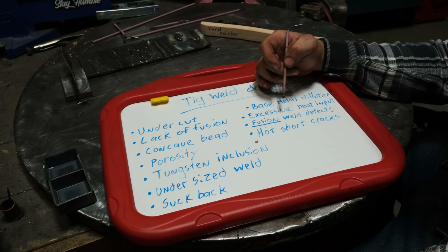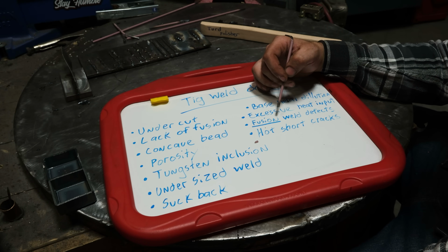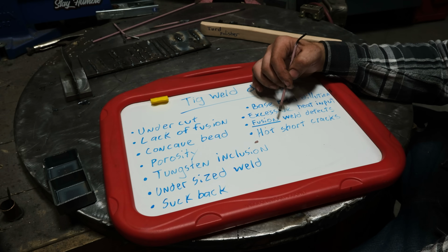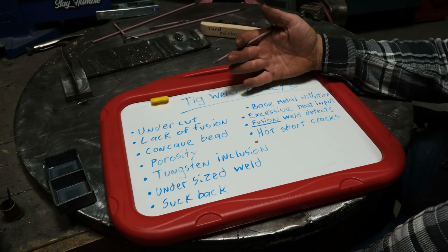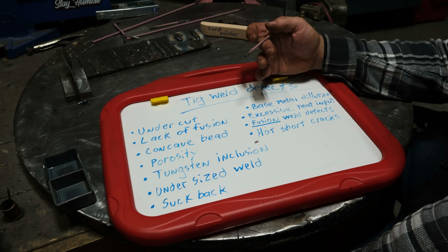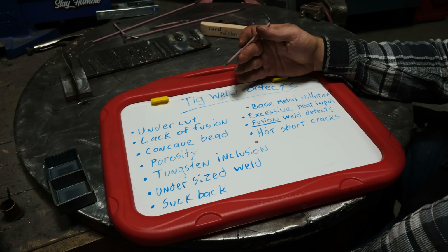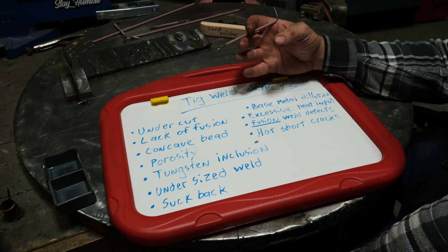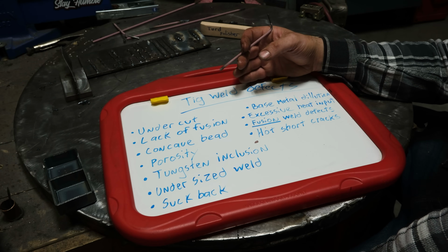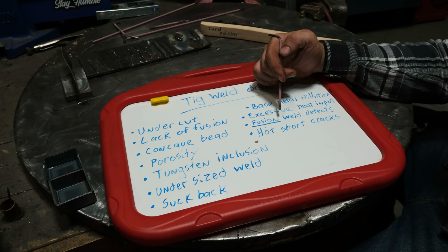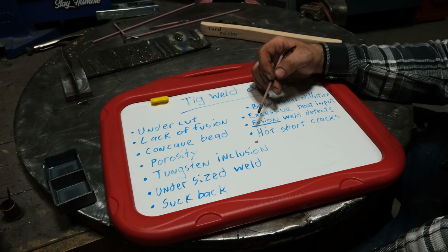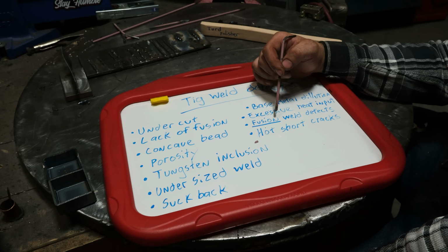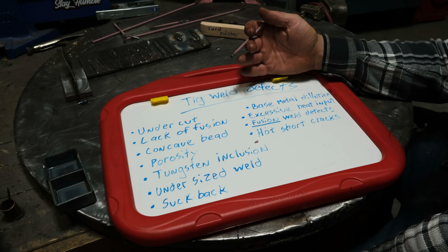And that is why, again, if you're screwing around with stainless or any kind of alloy that is sensitive to oxidization and it's thin, which is thin material, let's face it, that's when you're using fusion welding, you want to purge the backside of it with argon so that the weld is not oxidized to the point that you're going to have a failure of it. Again, I've repaired a lot of stainless headers that were improperly welded, fusion welded, where the welds crack, and it's due to the lack of an argon purge.